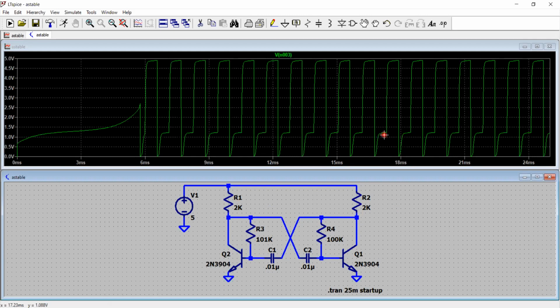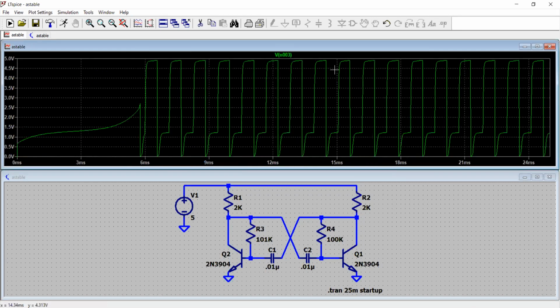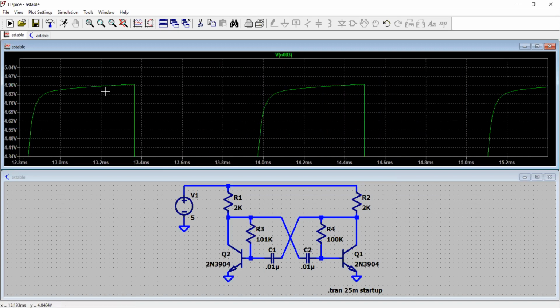There is a little bit of distortion here, but still it is catching up the oscillation at about 6 milliseconds. And then I have this pulse waveform that is steadily oscillating between these levels, right? So the on time and off time of this can be measured.